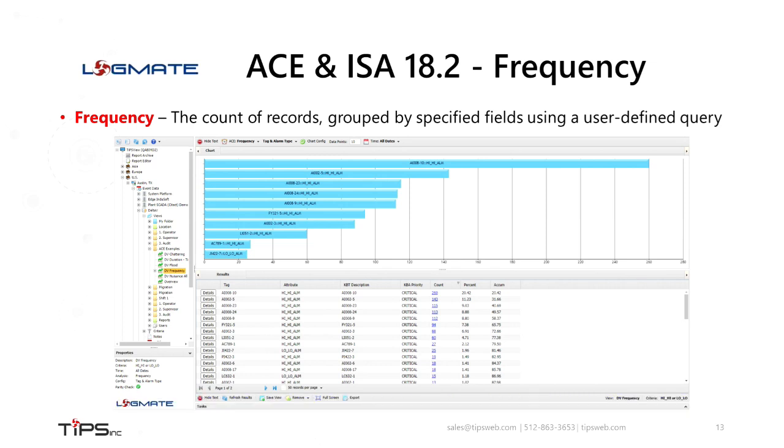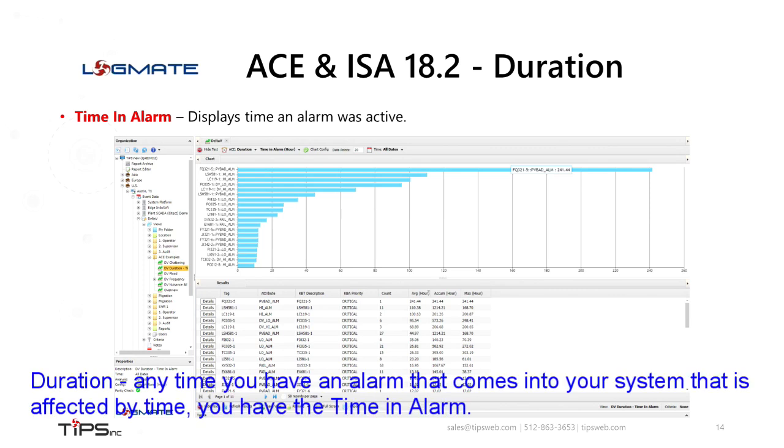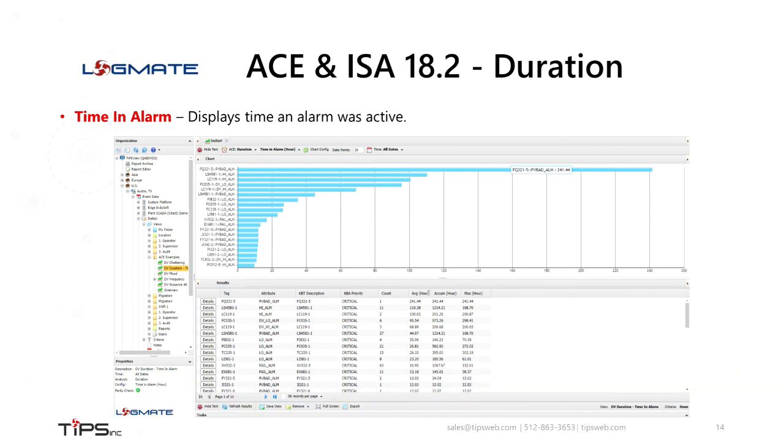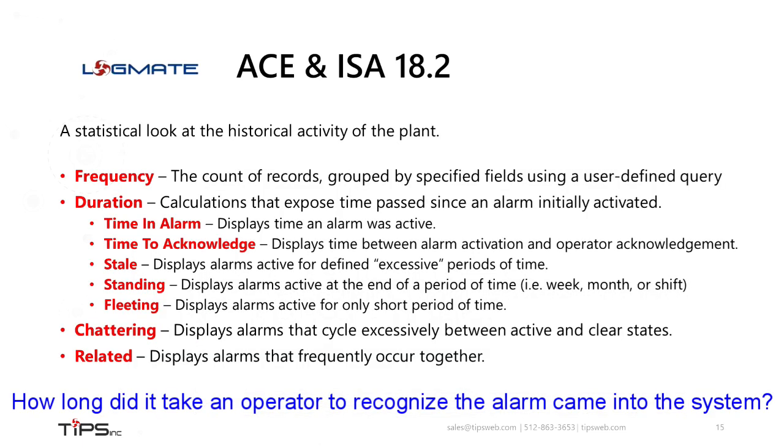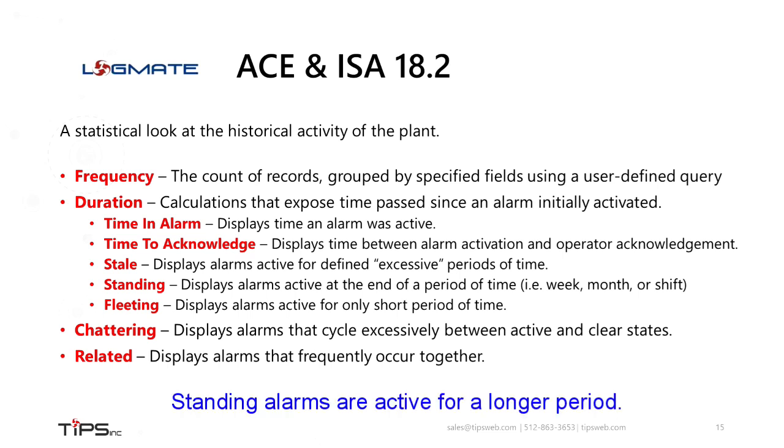Duration. In other words, anytime you have an alarm that comes into your system that is affected by time, you have the time in alarm. How long was this alarm active? How long did it take an operator to recognize that the alarm came into the system? Stale alarms stay in the system for excessive periods of time. Standing alarms are active for a longer period. Maybe it's a day, a week, a month.